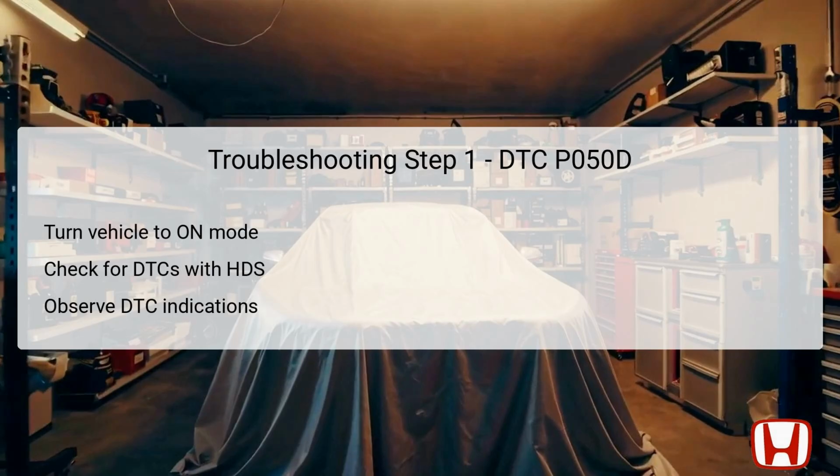If any other pending or confirmed DTCs are indicated, it will be necessary to address those issues separately, as they may be contributing factors to the cold start idle speed problem. Conversely, if no other DTCs are shown, you can proceed to the next troubleshooting step.